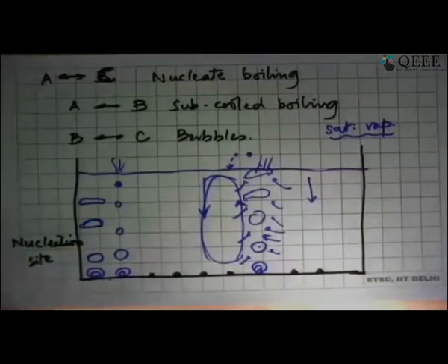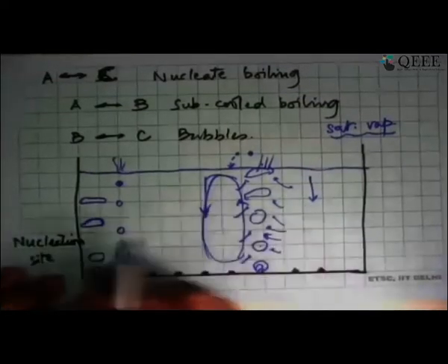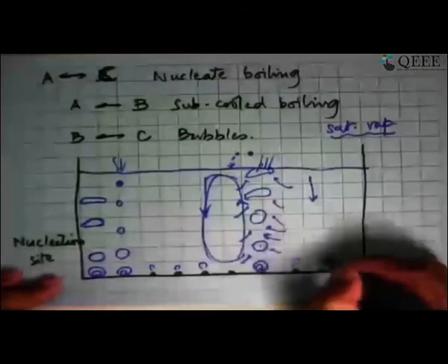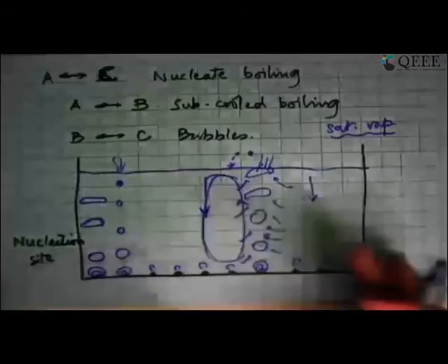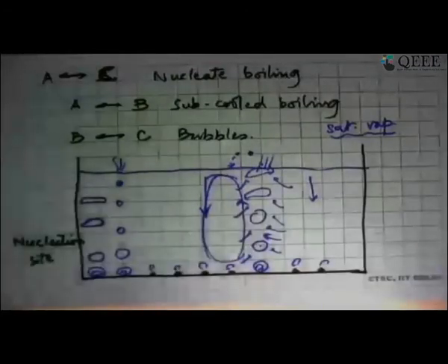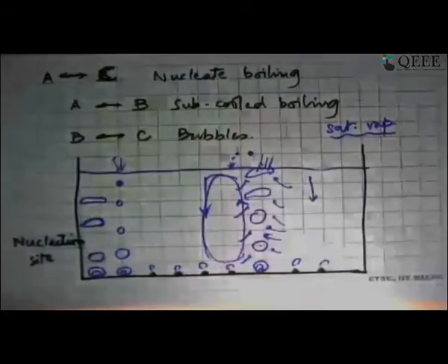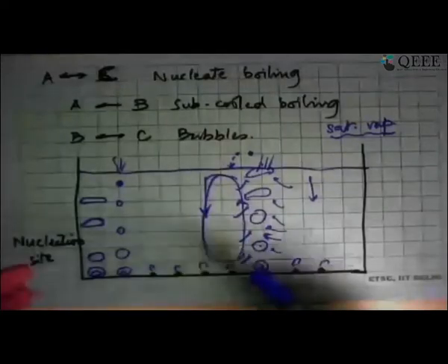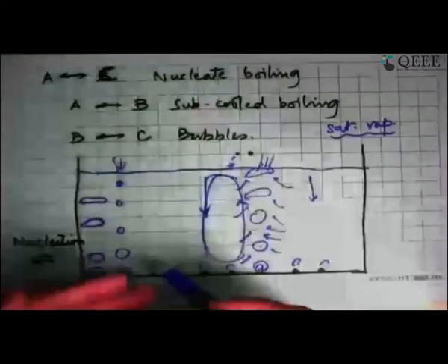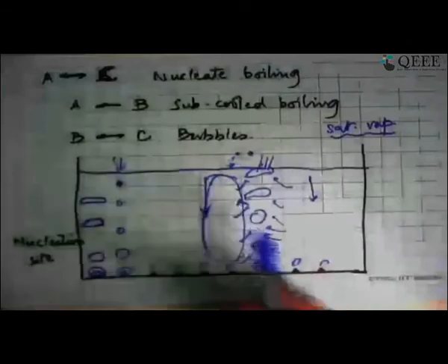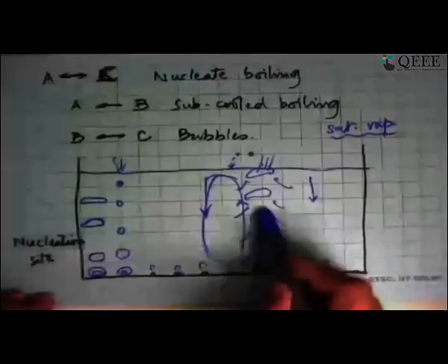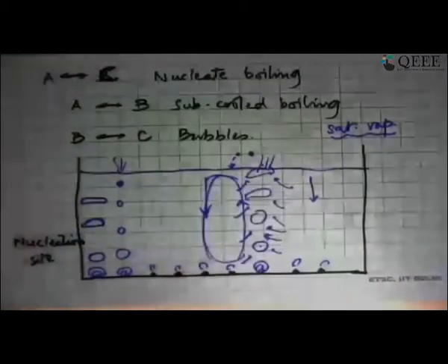And this is the nucleation site at which suddenly, where boiling was taking place only at two or three points, and that too maybe subcooled boiling, suddenly you start boiling and bubble formation happens all over the place. So this whole vessel suddenly bursts with a lot of bubbles, and they all come to the surface. If it was salt or sugar, in a couple of seconds that sugar or salt dissolves in the water, the nucleation site disappears, it reverts back to what we were seeing, and it again takes its own sweet time to get boiled up.